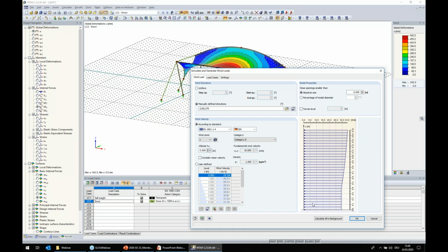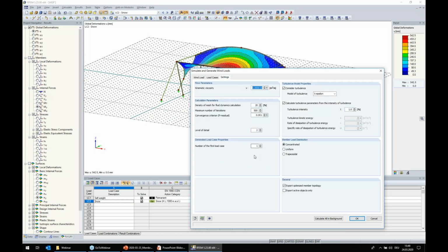But because I assume now that the gusts near the model will be induced from the model geometry itself, I define in the beginning of the wind tunnel a mean velocity and define near model. The program should react with a specific turbulence model, some gust effects. And here I assume a turbulence intensity of 10%.